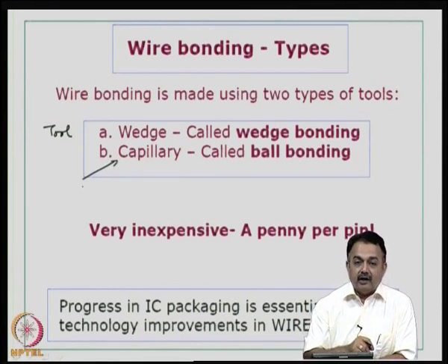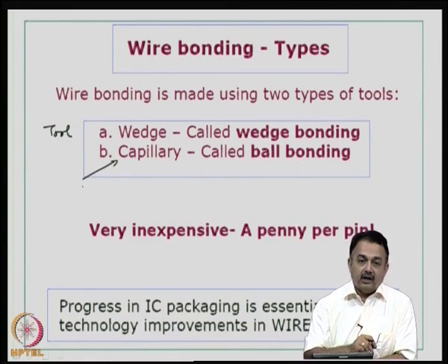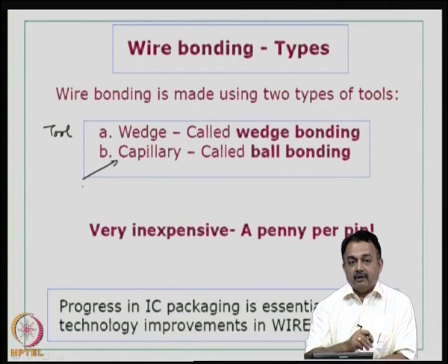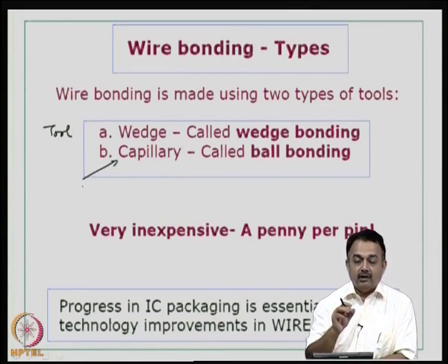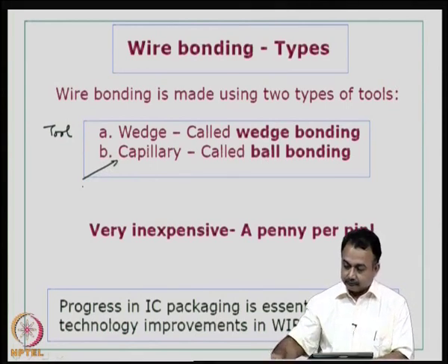Okay. The wire diameter depends on the space availability and the area that is available. If you are using a chip on board, directly on board, probably you can have more area to utilize, but if it is in a package on a lead frame, then you have to be very critical in choosing the diameter.